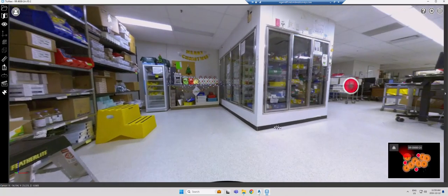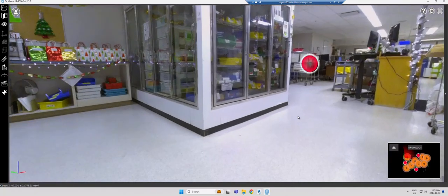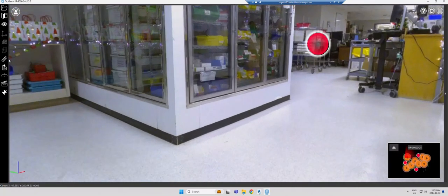And the really neat thing about this program is we're looking at high-res pictures, but there's also LiDAR data embedded in the background. So if I wanted to take a measurement on the picture itself, you can see my picking tool realizes that there's a plane change there. So if I pick right at the corner here and go to the corner here, there's the distance.